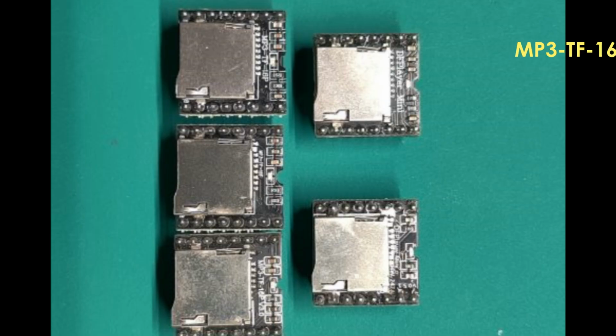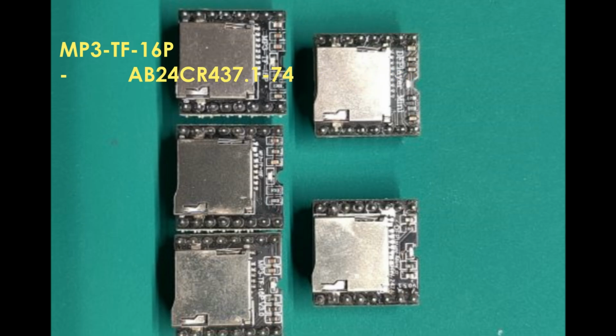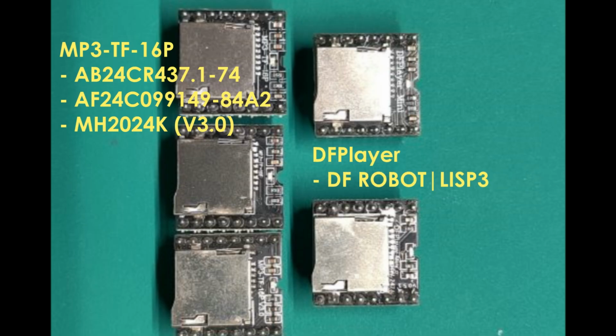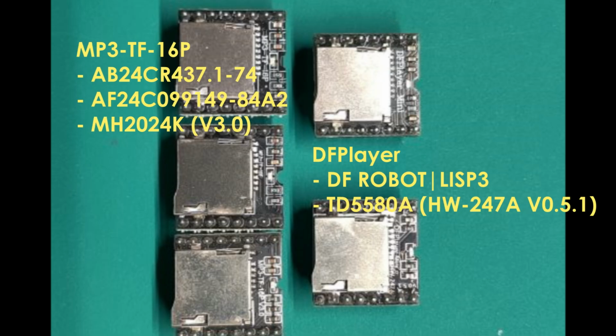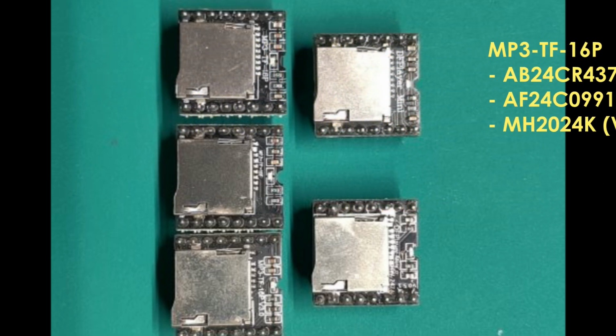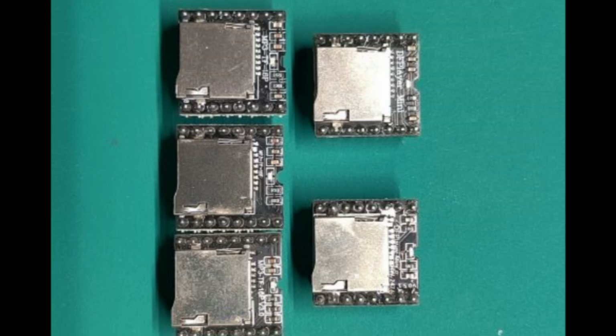In the review, there are three MP3-TF-16P, two have the JL chipset, and the third is an MH2024K. For the DFPlayer Mini, one is a DF robot, the likely standard to review by, and the other is a TD5580A. They all seem to use the 8002A amplifier chip. All the test data, command set, and player images are available from my GitHub link below.